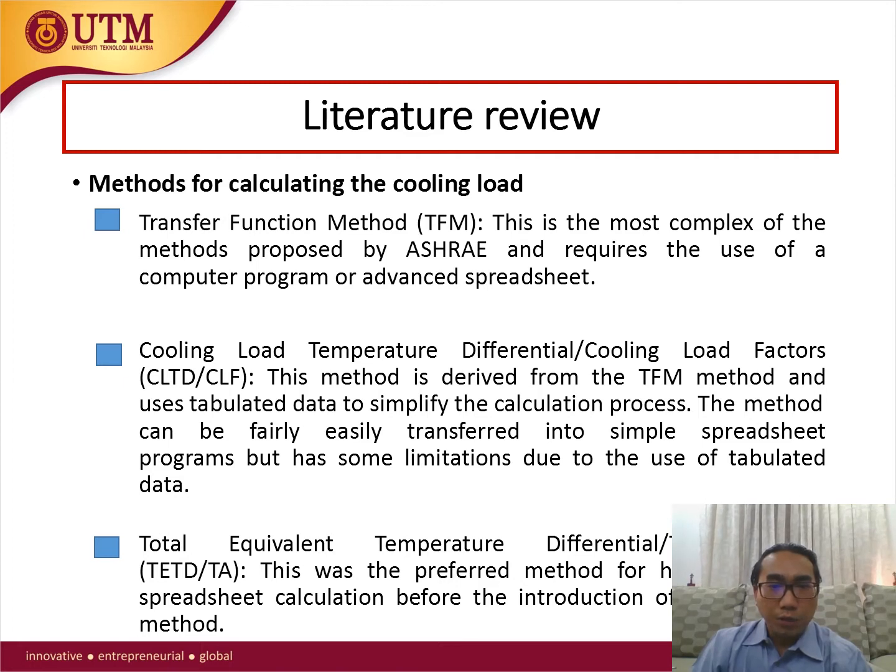Method number 2, Cooling Load Temperature Differential, Cooling Load Factors, CLTD, CLF. These methods derive from the TFM method and use tabulated data to simplify the calculation process. The method can be fairly easily transferred into simple spreadsheet programs but has some limitations due to the use of tabulated data. Method number 3, Total Equivalent Temperature Differential, Time Averaging, TETD and TA. This was the preferred method for hand or simple spreadsheet calculation before the introduction of the CLTD/CLF method.